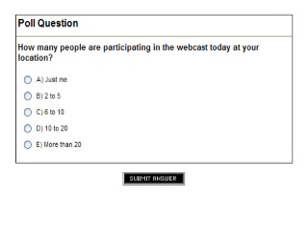What you find is when you're disinfecting these kinds of wastewaters, you're not practicing combined chlorine disinfection like you do at a wastewater plant. So you don't have to have the 15, 30-minute contact time. You're talking about 2, 3 to 5 minute contact time. The thing you want to do is get it dispersed well into the flow stream. And as we'll show you later when we talk about disinfection, you're likely having high doses of the oxidant to satisfy the different demands. There are going to be immediate demands that will use up that oxidant quickly, and then you have to have enough of it in there to kill the bacteria and pathogens. So to try to answer the question, with a small footprint, 3 to 5 minute contact time is not that large.